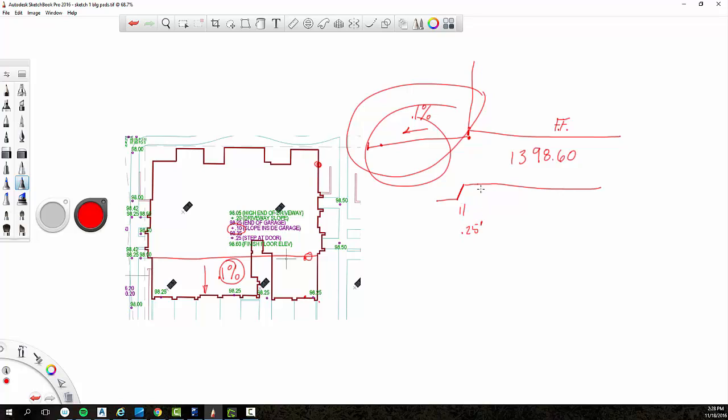What we need to know, I guess, is what I'm trying to say, is that you need to have some separation horizontally so that when the triangulation takes place within this area here, we're not having a vertical face. A vertical face would be the same elevation with no offset.